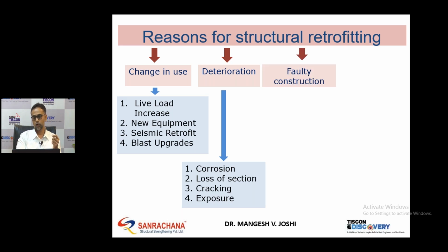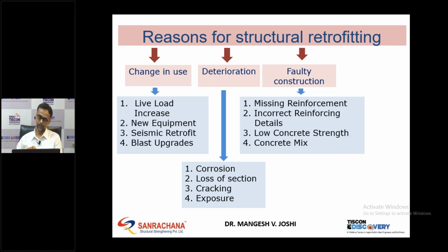Then this is also a very interesting area. We are getting almost 25-30% cases of faulty construction. Nowadays quality parameters have really gone up, and quality is monitored at every stage and reviewed by different agencies, and we found that reinforcement is not properly placed, or many times we find missing reinforcement or incorrect reinforcement detailing.